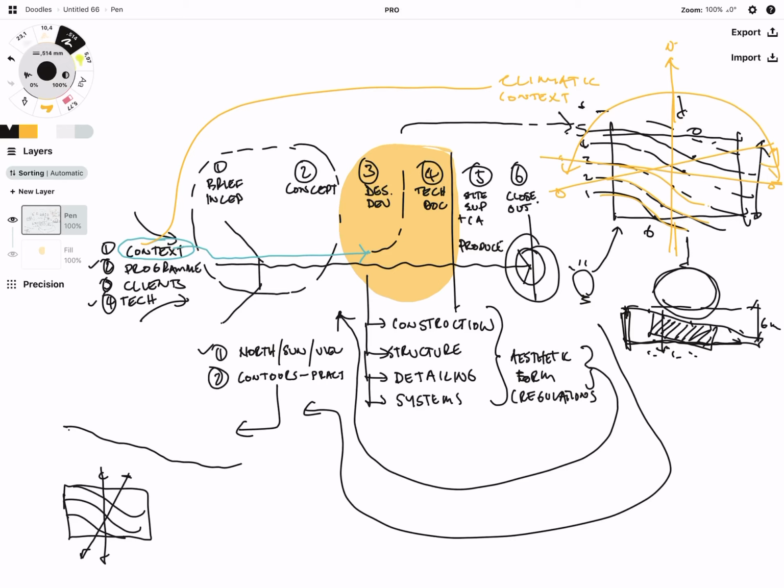So this relates to which position your building is going to be lying. If you are deciding to put your building on the ground, if you put your building perpendicular to the contours or in line with the contours, that's the most efficient, practical way you can do it, and that simply means that the distance between each contour is longer perpendicular to the contour than at an oblique angle if we had to do it this way.